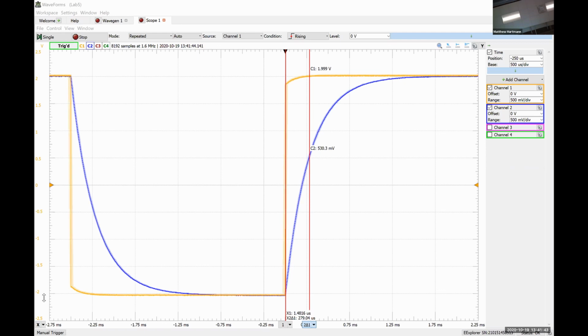That's exactly right. Whatever the function is at infinity. So in this case, that would mean that it's going to be whatever value the capacitor voltage settles to, which brings us to an important distinction here then. Are we going to look at a charge cycle or a discharge cycle for our capacitor? We're going to get the exact same value for our time constant. It's just going to change our equation slightly because we're going to have a different value of y at t equal to 0.